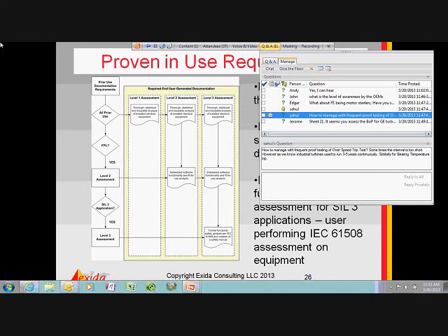So you might have to put in a means of improved diagnostics. Maybe you could do a comparison between the speed sensors for that, and on the trip valves you could do a partial valve stroke test, but obviously you can't close the valves unless you've got enough capacity through.